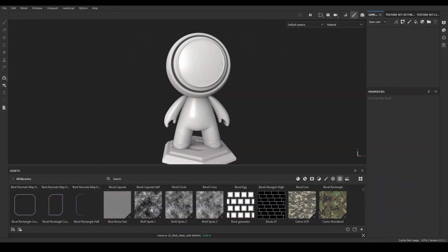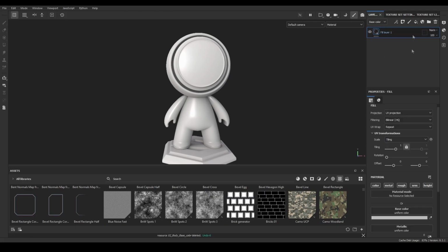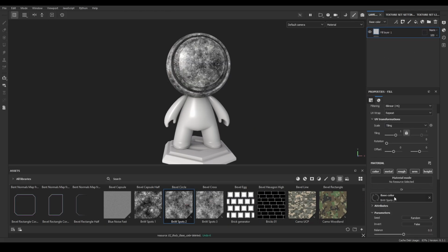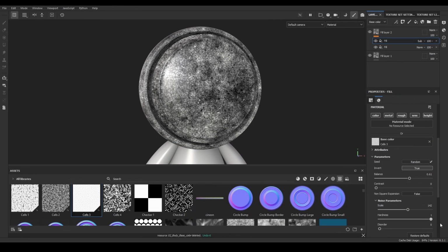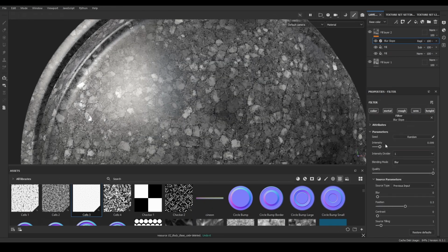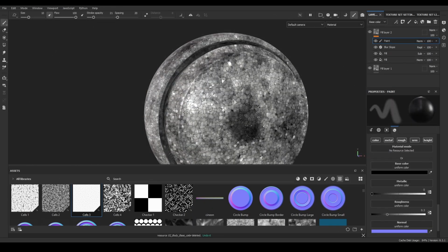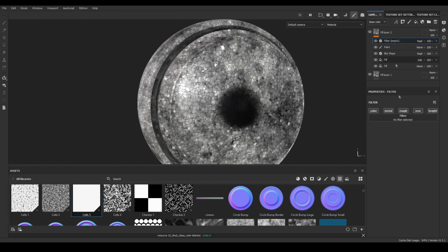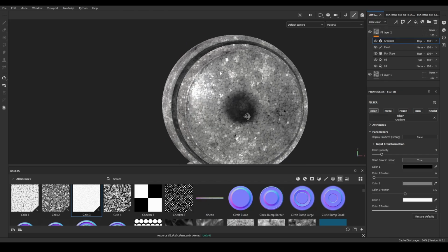To start, we need a new fill layer with some texture information. This can be as simple or complex as you want. You can work with just a texture or procedural added to the base color of the layer, or start making a very complex layer, combining different fill effects, filters, or even painting manually. Anything is valid to create a good base for our material. After we have set our layer, the gradient filter is added from the Add Filters option, like any other filter.